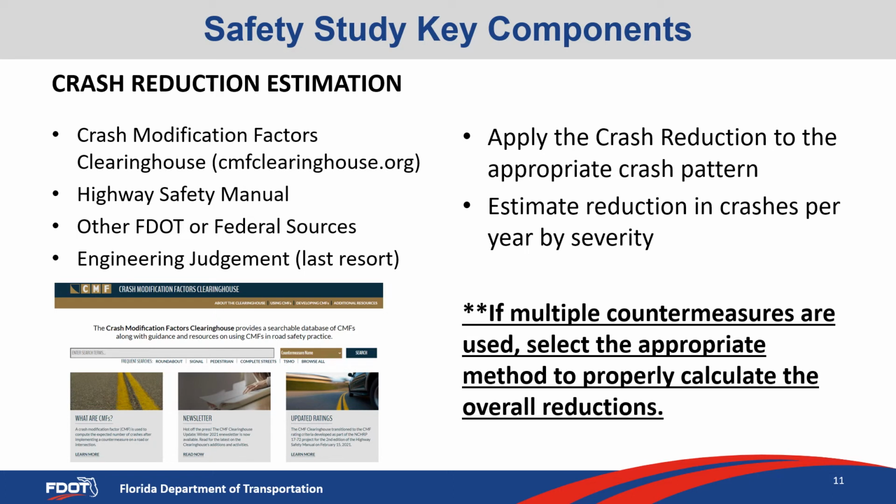During this review of crash reduction, at the end, you will have estimated the reduction of crashes per year by crash severity. Most typically, you would say it would demonstrate a reduction in X fatal per year, X severe per year, and X other injury crashes per year.